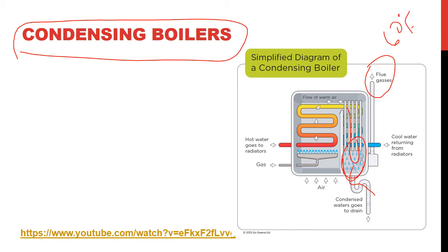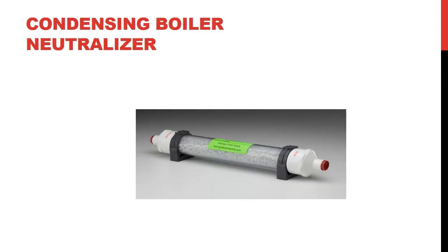Some of this condensation has sulfur in it, depending on what you're burning, some byproducts. So we have to install a filter for the oil, for the water, for the condensate before we can discharge that to the sewage. And it's a very, very smart idea to extract all the heat you can get from fossil fuel. This is a picture of the filters.